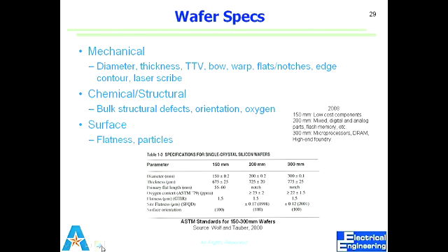And again, guess what? Do we want our wafer to be warped, or do we want it to be perfectly flat? Perfectly flat. Simple reason: we do many things where we might have it standing to do processing, but a lot of times we want to hold a wafer down on a vacuum chuck. A chuck is a round platform that has grooves in it, and we apply vacuum through those grooves. Once you put the wafer on top of that chuck, the vacuum sucks the wafer down. So it's very hard to move that wafer.